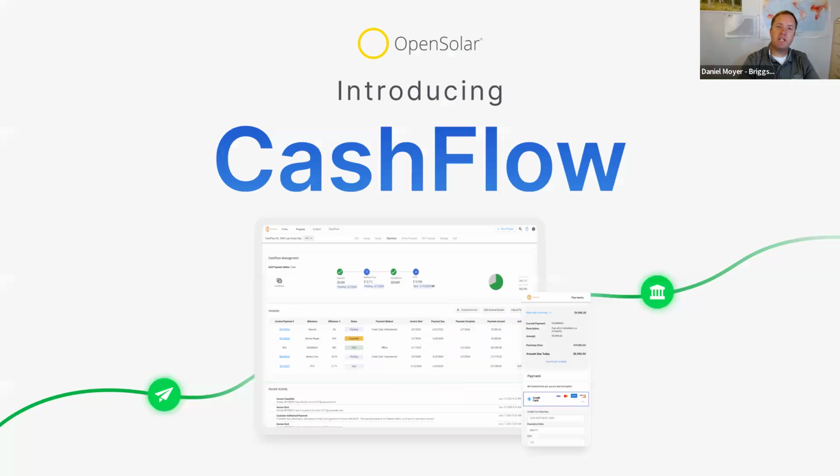Yeah, thank you. Absolutely. I was thinking a little bit more about that system, Andrew, that there are opportunities maybe to have a relatively small battery. Perhaps they are on net metering and they have a time of use rate, and we've calculated that the amount of energy they consume during that time of use rate isn't very much, so we don't necessarily need a larger battery. They're maybe on a very reliable grid, so they're not necessarily looking for a few days of autonomy. What we can do is sell them what they need and get the fastest return on investment, knowing that OpenSolar is going to model that for them. So, what's Cash Flow, Andrew?